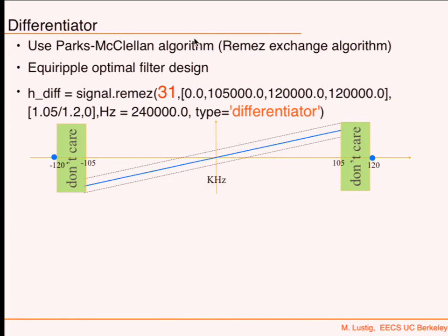You're going to use a function that implements the Parks-McClellan algorithm, which is also called the Remez exchange algorithm, which does an optimal filter design that, based on specification, will give you equiripple over frequency. So the ripple across the frequency deviation is going to be the same everywhere you design. It's a minimax implementation: you minimize the maximum deviation from the desired filter. We're not going to talk about it right now, but we'll talk about it a little later in class.